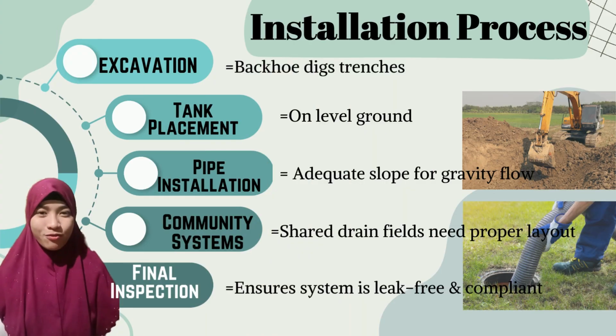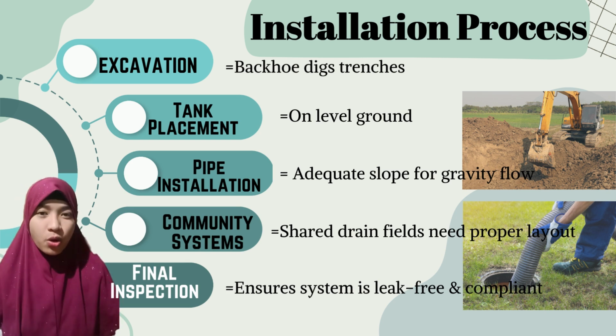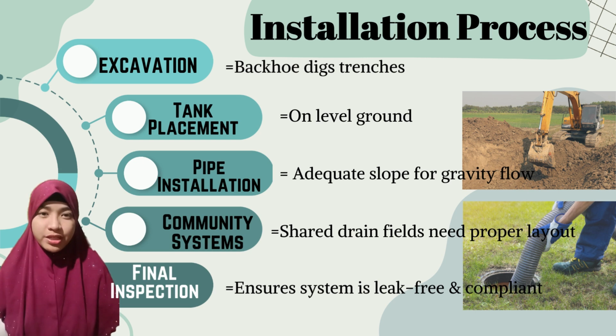Now, let's move on to the actual installation process, which involves several important steps. First is excavation. A backhoe is typically used to dig trenches for the septic tank, seepage pit, and drain lines. The depth and slope of the trenches must follow engineering guidelines.